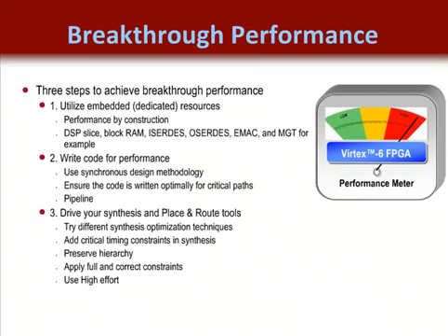This flow allows users to work around the limitations all synthesis tools have with regards to automatically inferring the best FPGA resources. The bottom line is that all of the high-end synthesis tools available for the FPGA industry usually do not allow inference of all of the best FPGA resources. Usually the latest and greatest will allow some inference support of the DSP slice and block RAM. Now, synthesis tools may allow some inference of these resources. There are plenty of exceptions, however, but usually only primary applications are inferable.